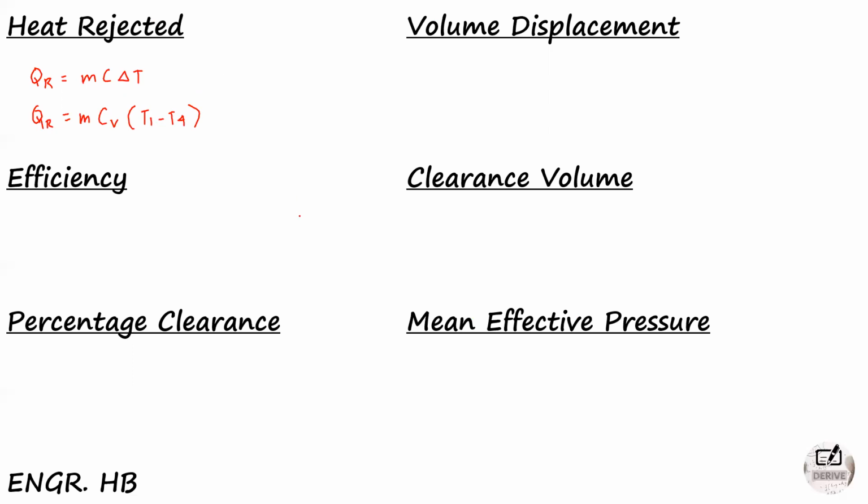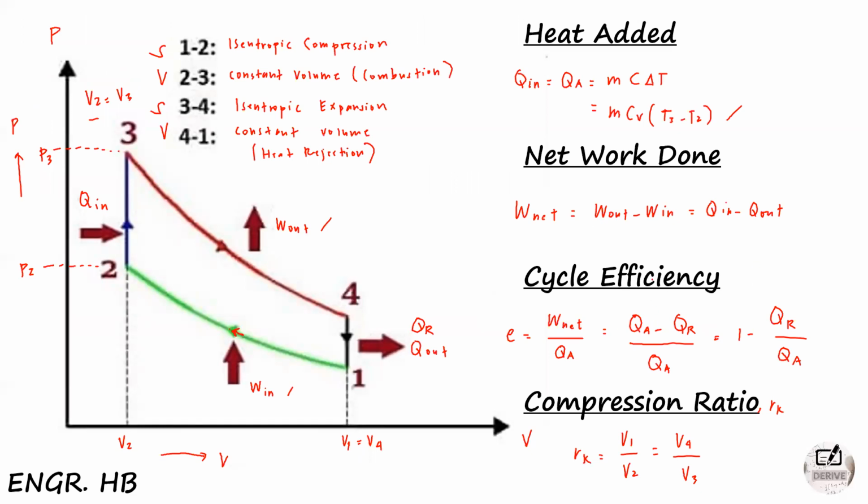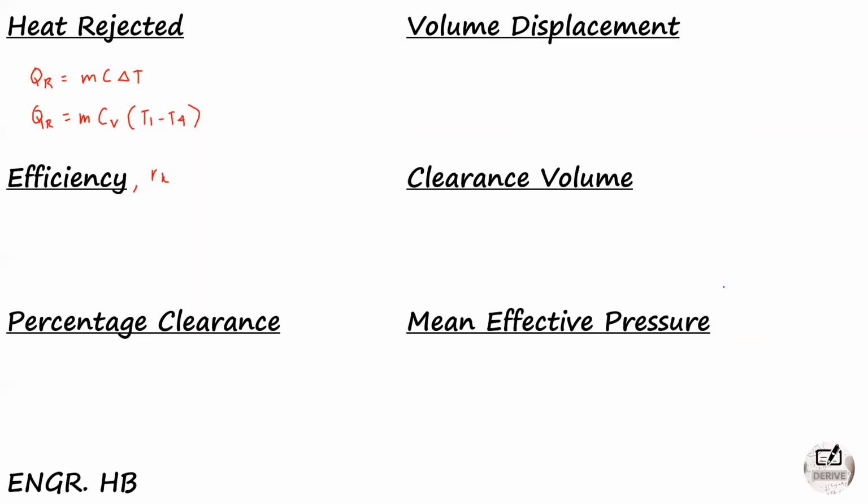Okay. So bakit may efficiency ulit dito? Kasi kapag usapang cycle, bida din lagi dyan ang compression ratio that you can insert inside the efficiency. So we may write the efficiency in terms of RK kasi kanina in terms of heat output yan tsaka heat input. Ngayon naman in terms of RK, so that was the formula: E is equal to 1 minus 1 over RK raised to K minus 1. Where K, of course, is the ratio between the specific heat at constant pressure and constant volume.